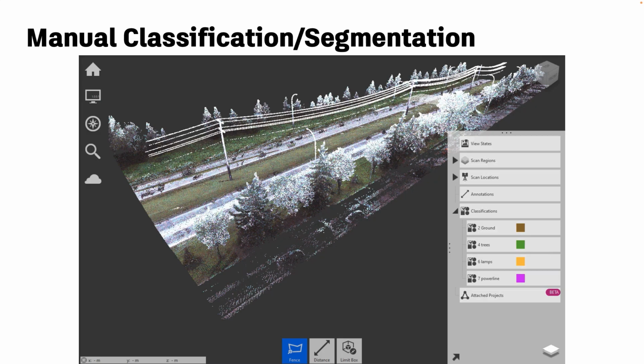I also said, this is actually not part of step 1, step 2, step 3, because most of the users like you use the feature lines as break lines, and you can take it from there. But imagine you have more information you can get from the point cloud data. I kind of alluded to it in automatic classification. You can classify the surface automatically, and obviously with this manual classification, I can clean up the way I want to, and I can take it into Civil 3D and create my surface, for example. But I hear some of you asking the question, Ramesh, I understand this, but it still has a lot of surface points.